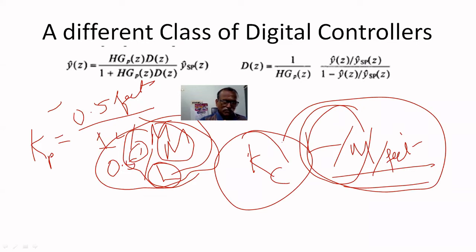That's why we have to see everything in percentage of controller output. That's why you always get a clash with the chemical engineers. As far as an instrumentation engineer is concerned, you will see the process as 0 to 100%. That's all. But a chemical engineer won't look at it like that. He will see it in terms of engineering units. That is correct, they should see it like that.